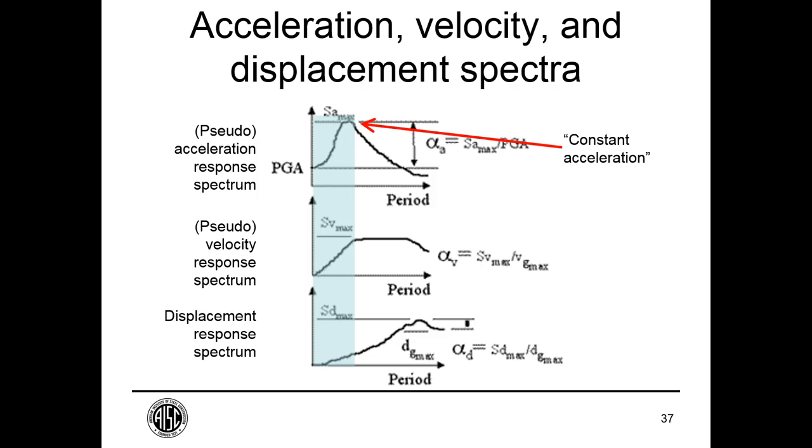At lower periods, the acceleration can be lower for design purposes. The codes, at least for the principal mode of vibration or the fundamental mode of vibration, treat it as if it's a constant acceleration from period 0 up to a certain period.